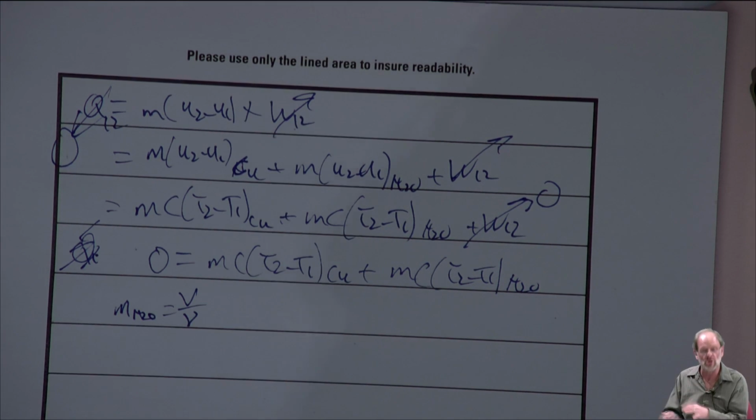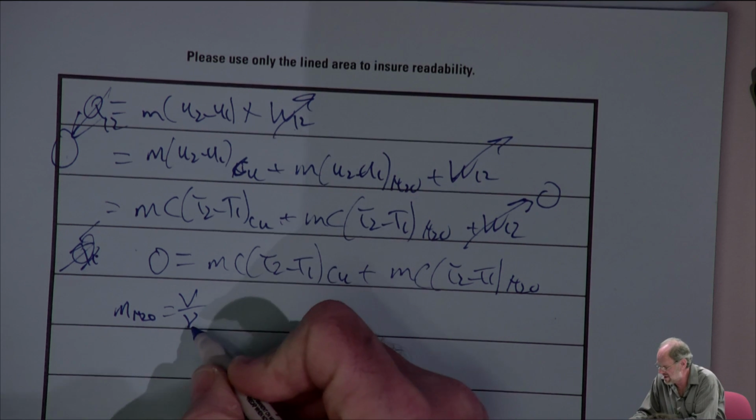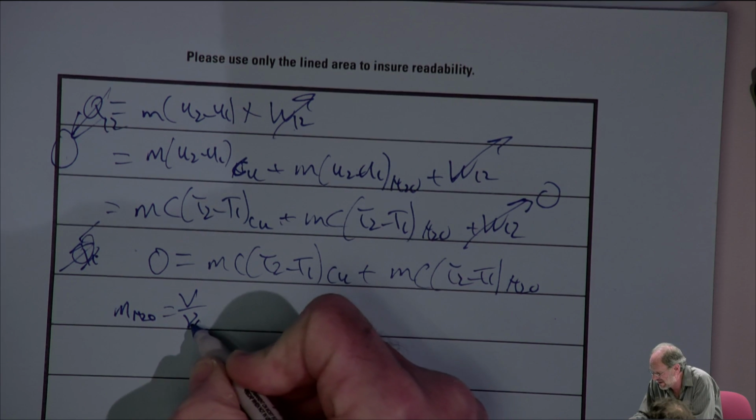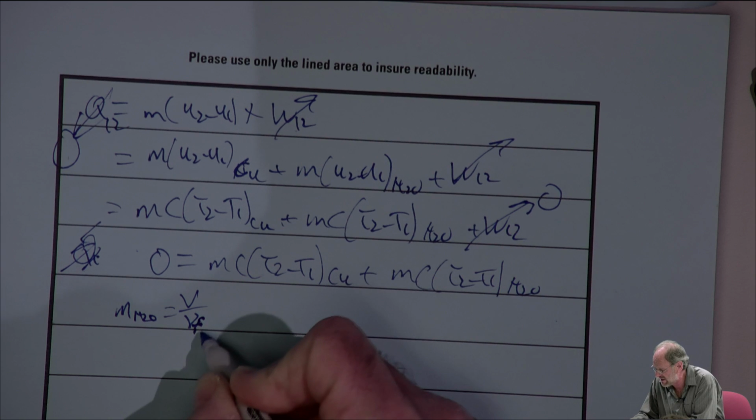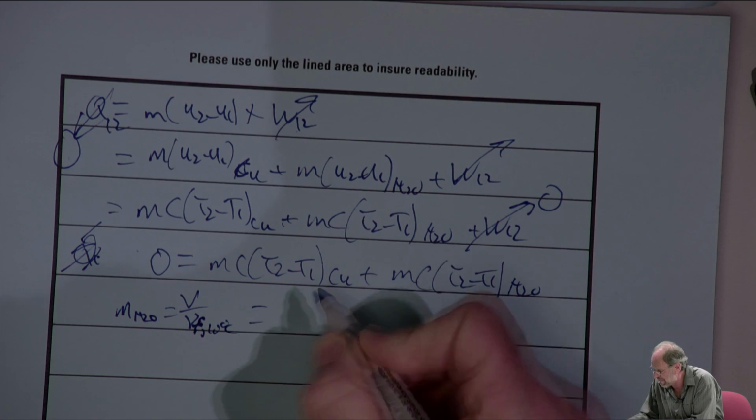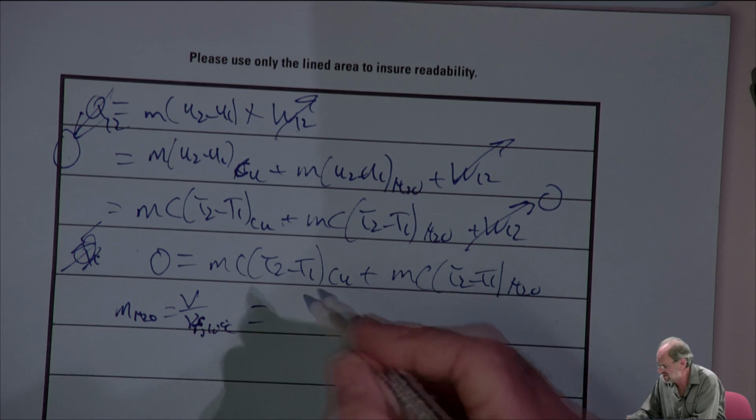Now, presumably, although they didn't tell us specifically, this tank just sits there at atmospheric pressure. And at the given 10 degrees Celsius, that temperature is well below the 100 degrees saturation temperature for water. We know that water boils at 100 degrees Celsius, right? So clearly, this is going to be a compressed liquid. In other words, the specific volume is going to be about the same as that of the saturated liquid at the same temperature. So we can find this right away.